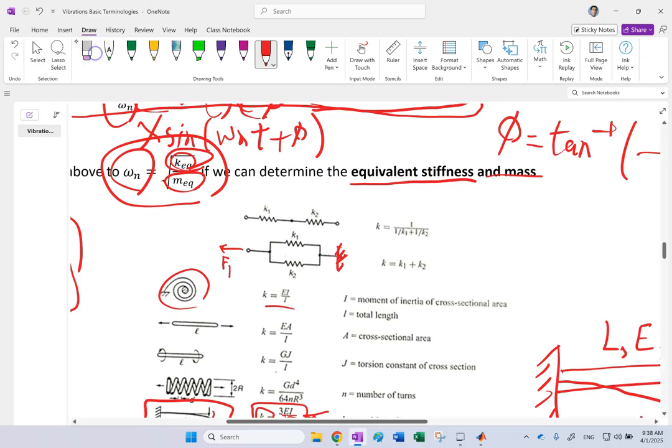So if I apply a force F here, good, you know that because these two are attached to these two fixed plates, their elongations, if you call them delta 1 and delta 2, should be the same. Otherwise, these two plates will not stay vertical. So in this case, delta 1 should be the same as delta 2.